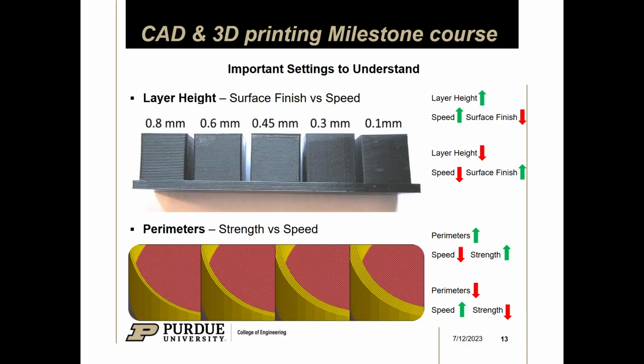So for the 3D printing process, again, it slices your model into a bunch of sections and then it prints a 2D profile of what it sees, right? So when it slices it, you can change how coarse it is. And when you do that, it can affect the printing time. Just because if you have more layers, there's more places for your printer to move and it'll take more time, right? But if you have fewer layers, less movement, less time. But you do get some trade-offs, right?